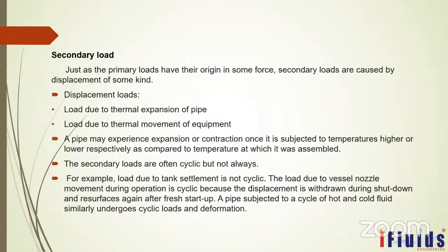And the second one is secondary load. Secondary load is also caused by displacement; there will be a secondary load. What are all the displacement? I mean, secondary load means load due to thermal expansion of the pipe and load due to thermal movement of the pipe. Whenever there is a liquid flow or a fluid flow, there will be some expansion or contraction. Whenever you start the plant, there will be some expansion. Whenever you stop the plant, shut down the plant, there will be some contraction if it is a high temperature. So those kinds of load come under the secondary load.